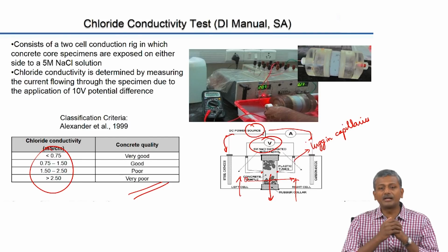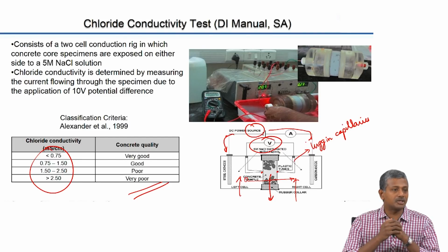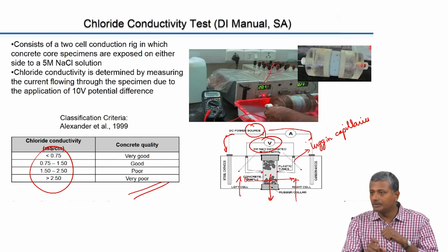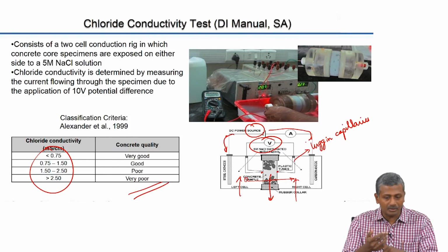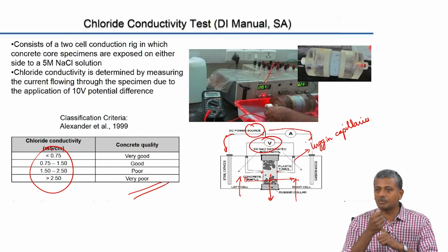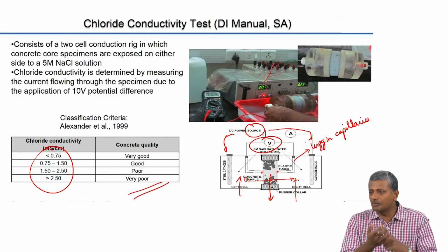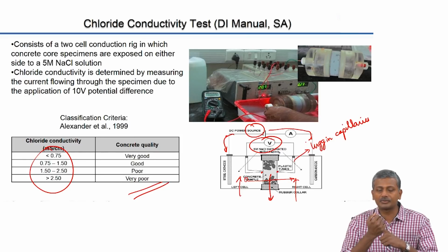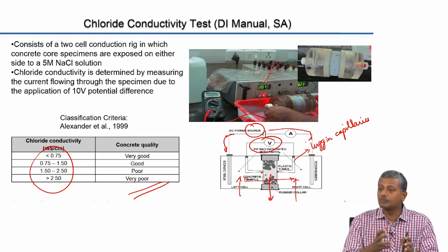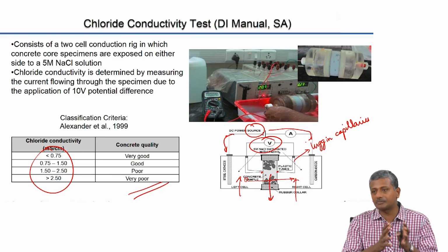Okay. The only difficulty lies in establishing where they can do the test, because the laboratories where the tests are done have to have a proper working system. For example, the oxygen permeability cell has to be properly calibrated, the chloride conductivity apparatus has to be properly set up, and so on. For water sorptivity you do not really need anything other than a balance, so it is not that difficult anyway, but vacuum saturation has to be done for the specimen, so that is something different.